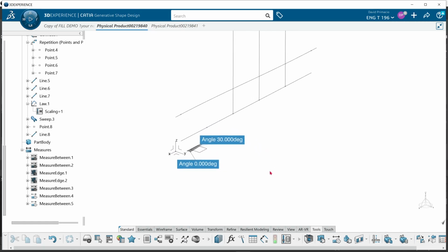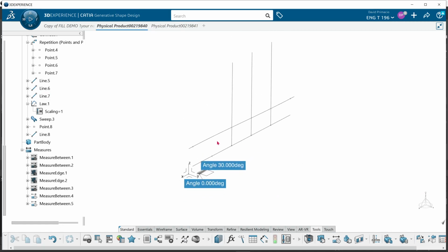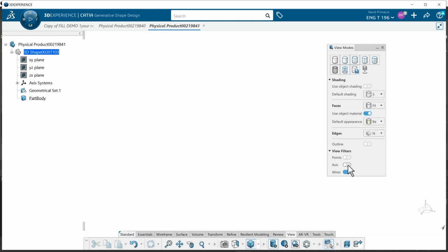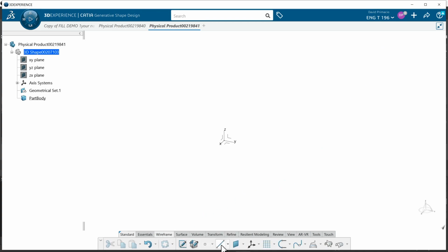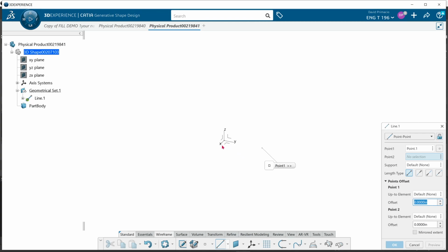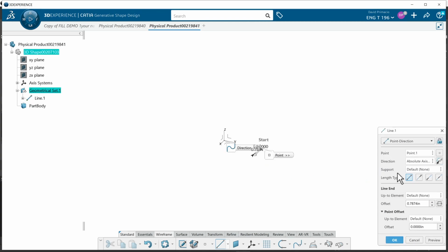All right. So that's how the angle laws are done, using no longer inches. You must use millimeters. Every 1 millimeter equals 1 degree. So if I were to start this from scratch, and turn these back on, go to Wireframe and create a line, insert a point 2 inches in the Y direction along the X, and go 10 inches long. Reverse the direction here. Select OK.